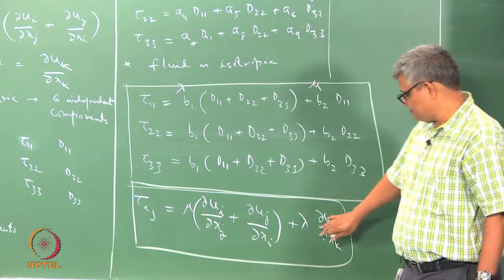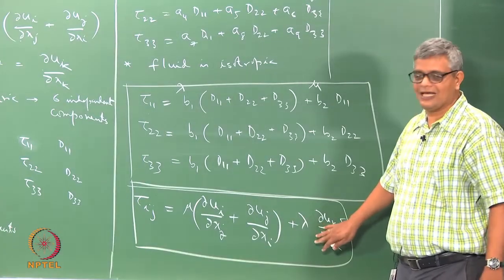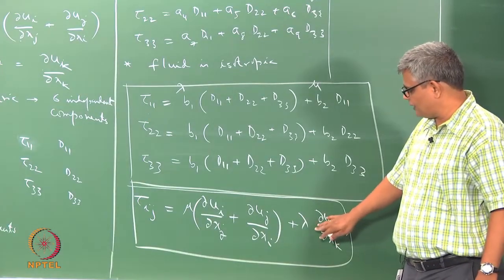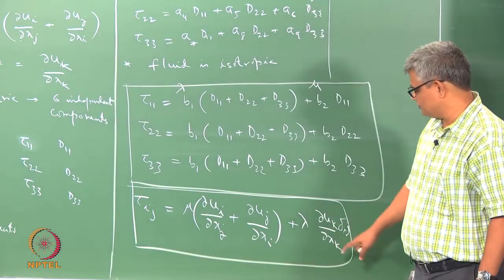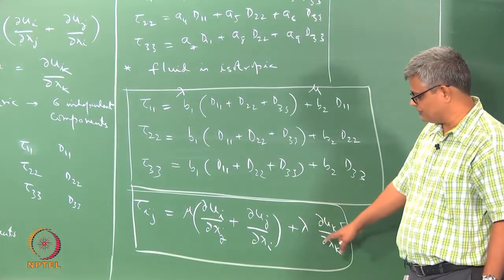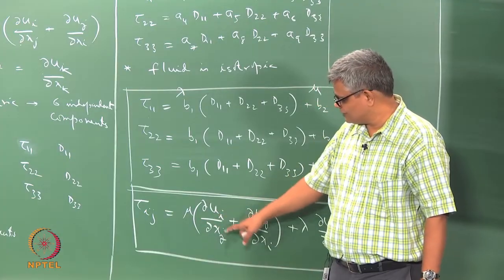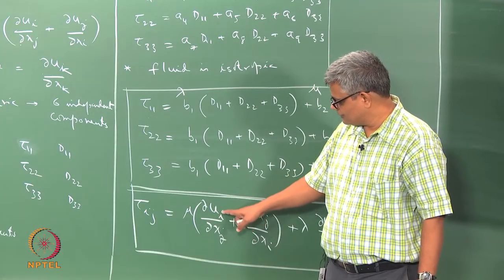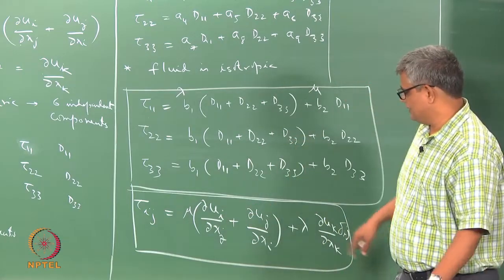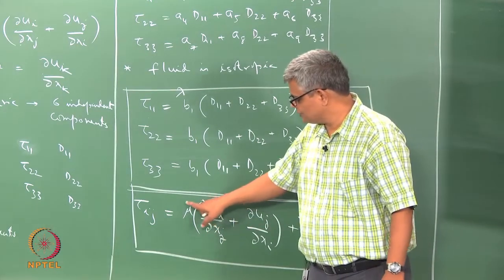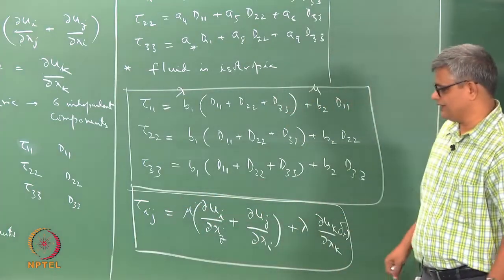This can be obtained for some simple gas species as having a certain value, but otherwise it is not possible to get an accurate estimate, whereas viscosity is something that can be measured in special cases where we impose a velocity gradient by rotation between two cylinders and so on. So this is easily measured. So we measure the viscosity and then we make use of this relation here.